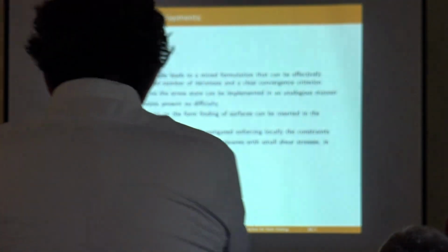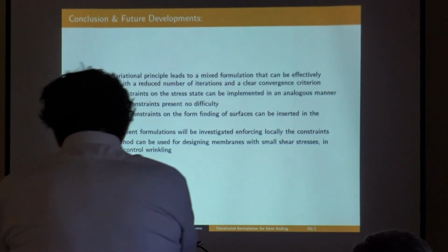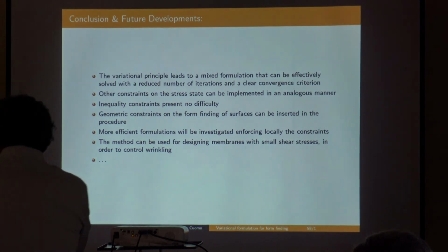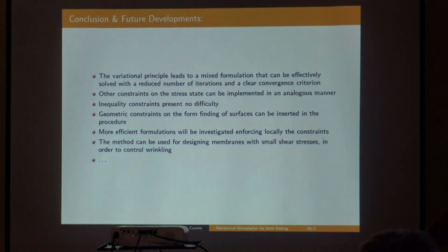Actually, it is easy to enforce the length by enforcing elements of equal length. This gives you a more regular solution. So you say I divided my catenary into 10 elements, and each one is 1/10 of the original, of the reference length. This is easier to enforce, and the more stable. If you have some elements very long and some very short, there can be some numerical problems. But anyway, it's a technicality.